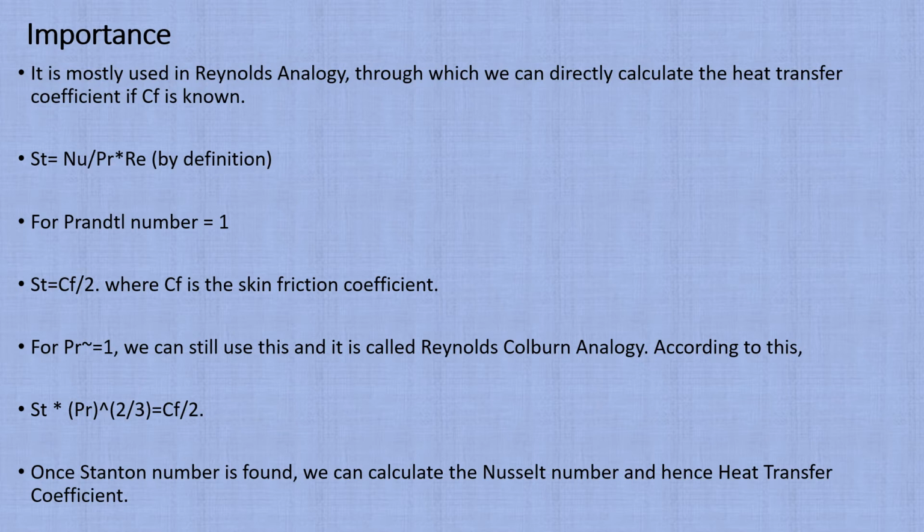So this is a very important mathematical relation in order to calculate the skin friction factor and Stanton number. Then finally we can also calculate the heat transfer coefficient if we know Stanton number, because if we know Stanton number, we can calculate Nusselt number, and if we know Nusselt number, we can easily calculate the heat transfer coefficient. So you must keep this important ratio in your notebook, because it is also asked in many different tests.